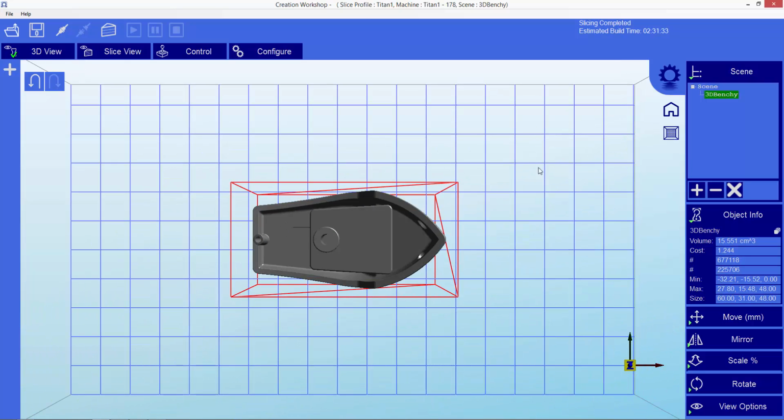And in particular, the projector has best focus in this area here, which means kind of from the center all the way down to the bottom of the projected area. Now, when we look at it this way and think about how this is mapped to the vat, this is from the projector's perspective, right? And so when we are looking at this projected view, it's as if our eyes were at the projector looking at the vat. I mean, we're looking at the vat from the underside, right?